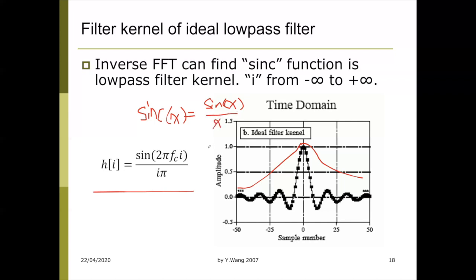It's probably not as common as other trigonometry functions. The property of this function is that when x equals 0, it defines the value as 1. Otherwise, this function would have no meaning, as we can't have anything divided by 0. But we specifically say when x equals 0, the whole thing is equal to 1. When x increases, on both sides, negative or positive, this number becomes smaller. So that's the sinc function. To get to the ideal filter we showed in the first picture, we need to have this sinc function, but with infinite length.